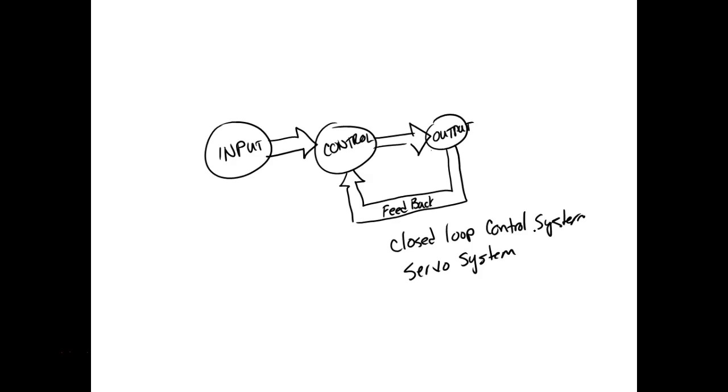So what do we mean by feedback? Feedback means I tell my actuators what to do, and then I verify that it's been done. Now what's this going to come from? Sensor. That's right. That's exactly it. So just about everything we have over there is closed loop. Not everything. We can watch that robot go over there, and I don't have any pistons over there, and the robot just goes over there and goes down and clamps it down. So there's no feedback in that system.